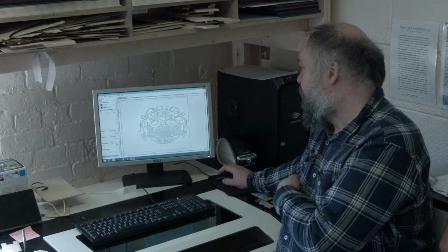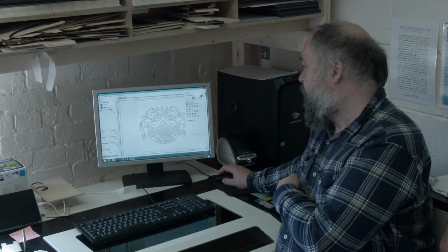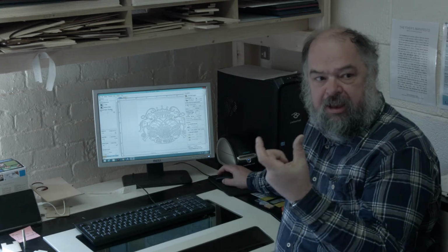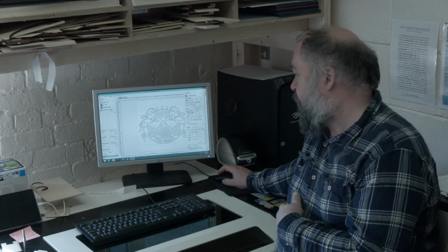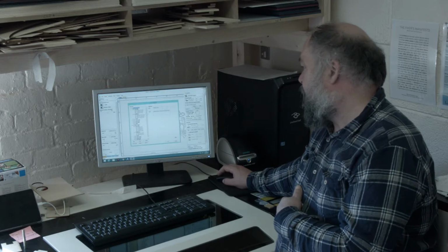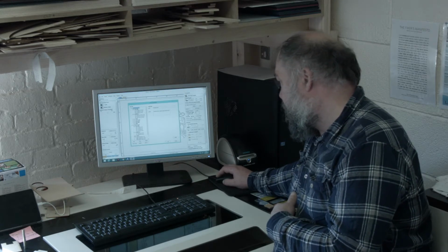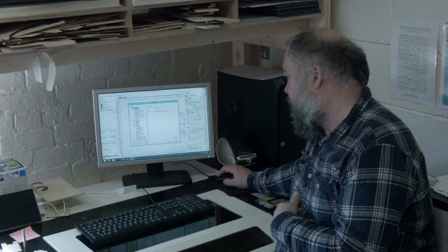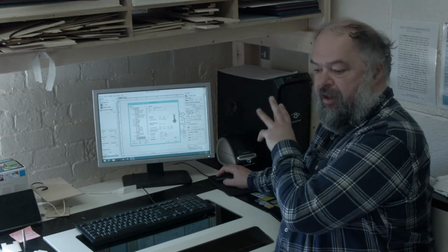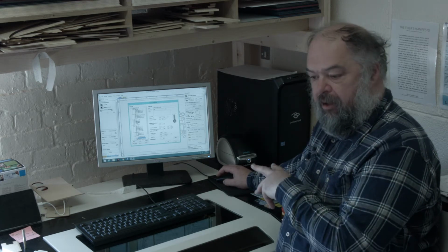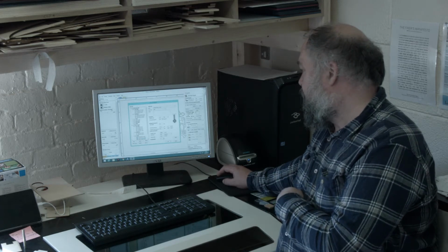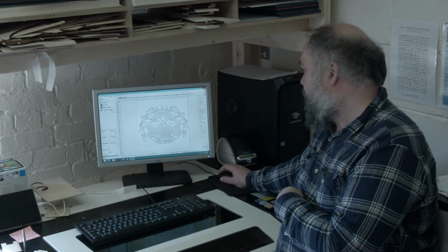So apply. Now I can go into my toolpath, and this is what they call a V-carve toolpath. You get a bit which is like an angle at the bottom, and then you can say how it's going to do it. So again, select my tool. I'm going to go to a V-bit, and I want a 90-degree 12mm V-bit. All the speeds and feeds for how to run it on the machine are on here as well, so he sets all of those from it. That's a really nice library.